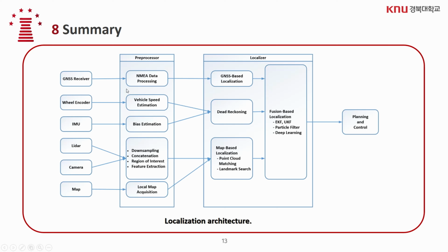Then also for the ground truth analysis, mainly we need to consider GNSS based localization. The main challenges arise when the vehicle is in an underground car park or a tunnel. At that time we cannot depend on the GNSS data, so the system completely depends on lidar based localization. And outside, not covered by buildings or trees, the GPS data is very accurate. But the combination of GPS data, LiDAR data, and the IMU sensor or camera together obtains the vehicle localization. So that is the key idea of localization.